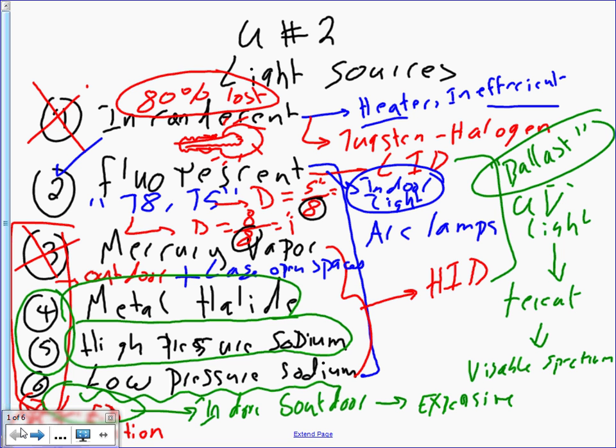In this case, it's 3 minutes. After 3 minutes, the fixture will come up to full speed. So, long story short, when you have a high intensity discharge fixture, you have to be aware that when you turn it on, it will take a couple of minutes to warm up. The voltage ramps up, the output will ramp up, and the current starts high and goes all the way down to full load current. That's what this curve is telling you. Any question, guys, about this curve?